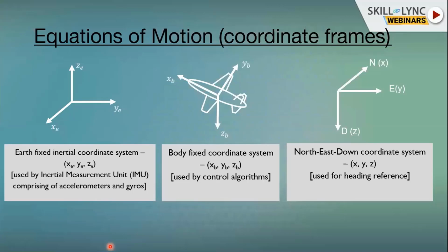The gyro is a system that can be reset and continuously integrates the body rates as the aircraft moves. It has a gyro underneath that determines the body rates in all three axes. That's the purpose of each gyro. So it knows what the aircraft is undergoing, and it keeps integrating to provide the attitudes.